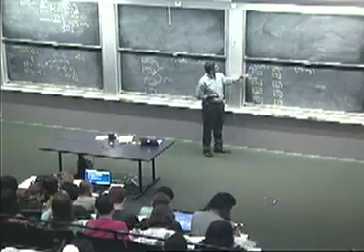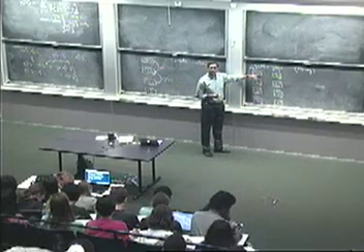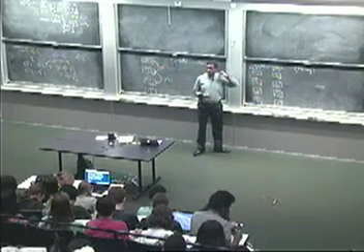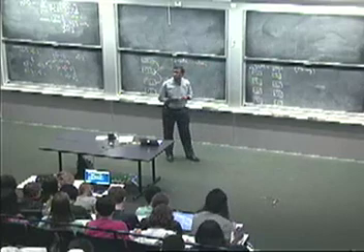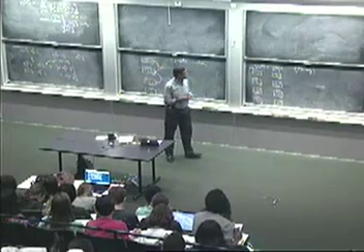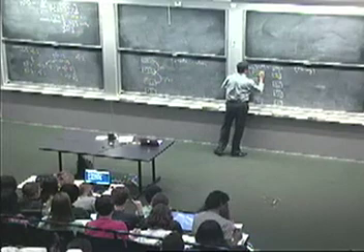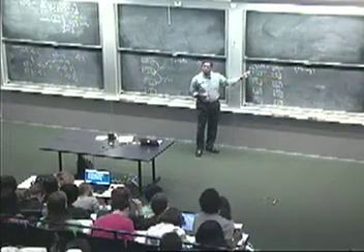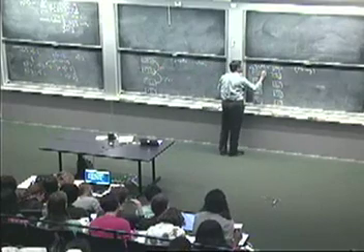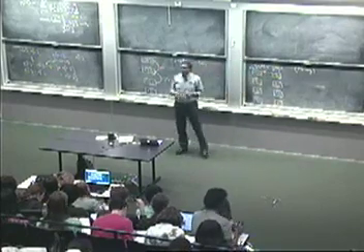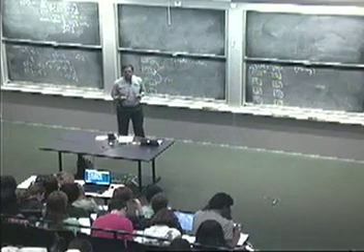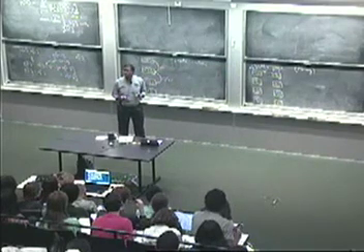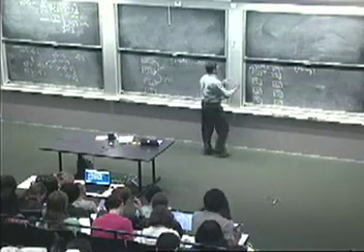At time n equals 0, I'm in 0,0. Suppose I get the input 0. Suppose the input is 0. What state do I transition to? Here, right? So if I have an input 0, I'm going to transition here. So this is with an input of 0. And what are my parity bits going to be? Both zeros, right?